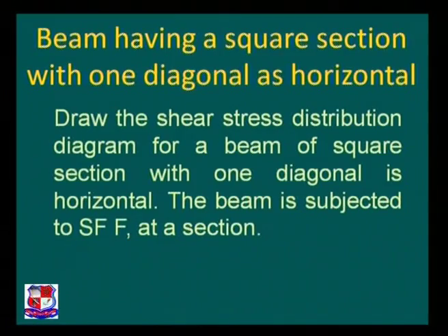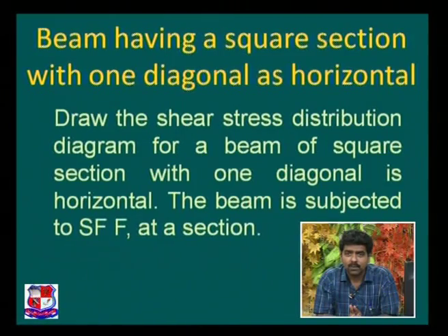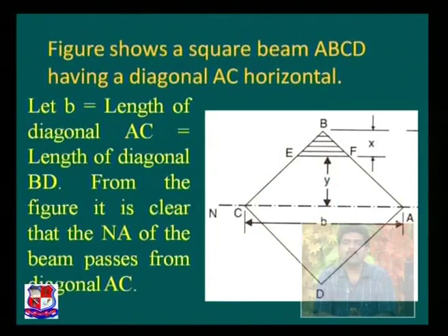Here a square section is given. It is to be placed diagonally, in which one diagonal is horizontal. The section is subjected to the shear force F, and our intention is to plot the shear stress distribution diagram along that particular section. Let us refer to the particular figure.